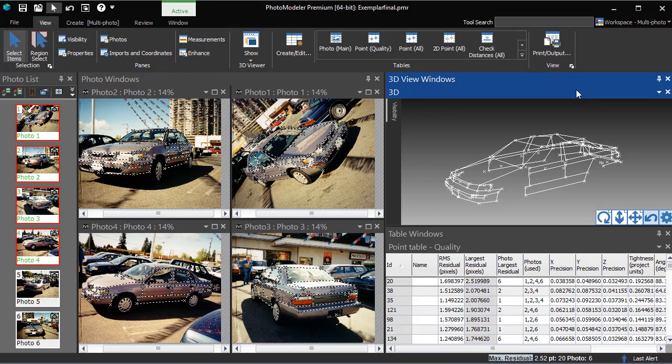points. Since nothing is known about the camera that took the crush photos, to be able to solve this project, you must have some known information about points on the uncrushed part of the vehicle. This exemplar vehicle is surveyed to extract 3D coordinates to be used as control points, which are needed by PhotoModeler's inverse camera to solve for the unknown camera parameters. This information could also be measured using other survey instruments, such as a total station or a laser scanner.